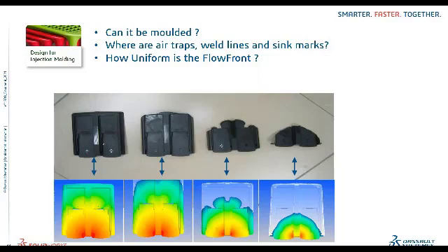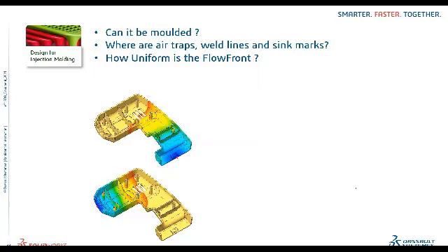So here we can see the full model, and when we have shot conditions, we can see what the final outputs are. This is how we can see the filling time. We will be able to understand the amount of fill and the location of the gates as well. Here we can see this is one gate location and here is the other gate location. So which one is faster? Which one is taking less time? Which one is giving us less pressure in order to fill?